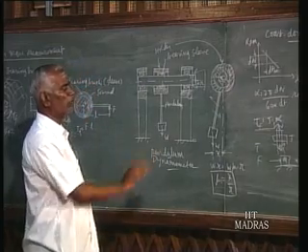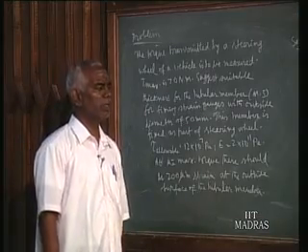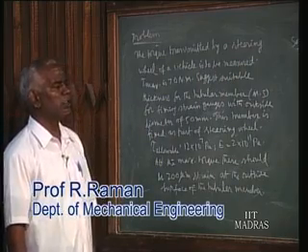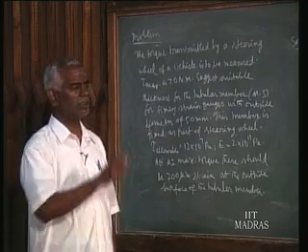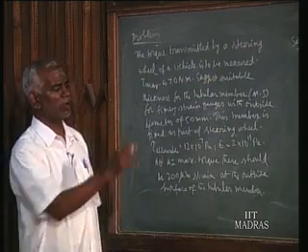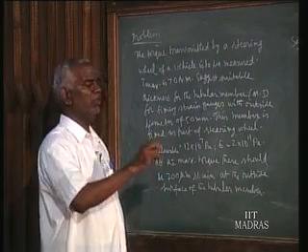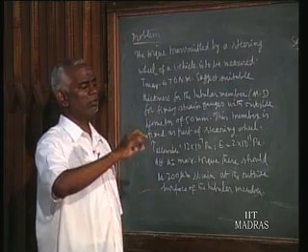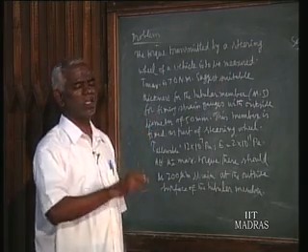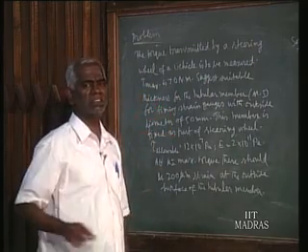From that we can find out what is the friction torque in the bearings. It is very important for a mechanical engineer to design the tubular member when you want to measure the torque in any transmitting shaft. As I already mentioned for the strain gauge torque meter, where we want to paste the strain gauge, it should be made a tubular structure so that we have sufficient strain there. Secondly, a tubular member will have large area so that we can easily fix the strain gauge.